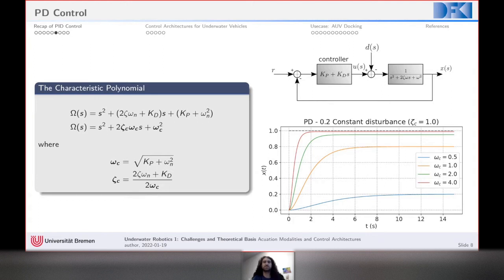And this means that your command or your actuation is, let's say, a thruster, which is what we're talking about. This means that you are pushing your thrusters really hard to be able to achieve the control that you want, which is not a very good thing to do. You are basically reducing the life of your hardware, or you are causing the system to reach some kind of unstable response. Now, how do we get rid of this?